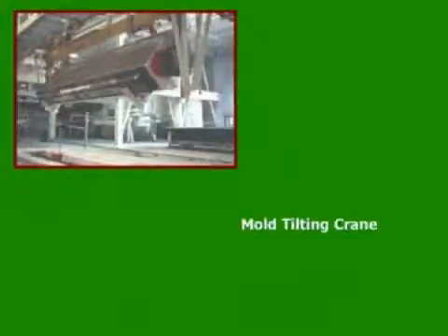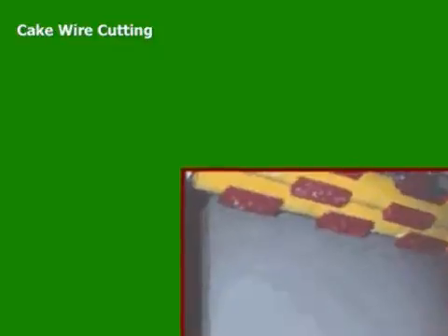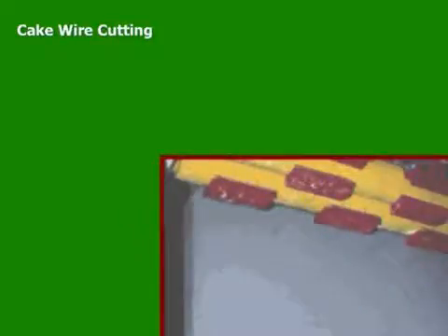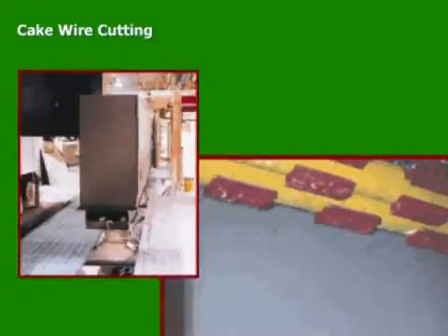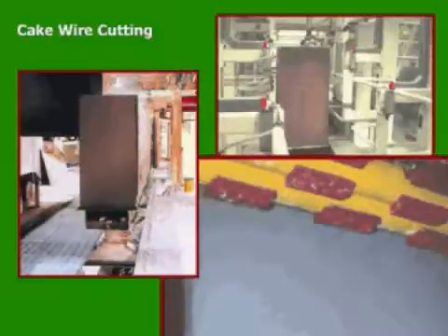Also the cement reaction occurred so that the material is stiff enough that we can unmold the AAC. Now the material is ready to be cut to size. As you can see here, those very fine wires, like piano wires, will cut the material in 2-inch increments. They will cut the material very accurately. All remaining material which is cut off will be recycled and reused.